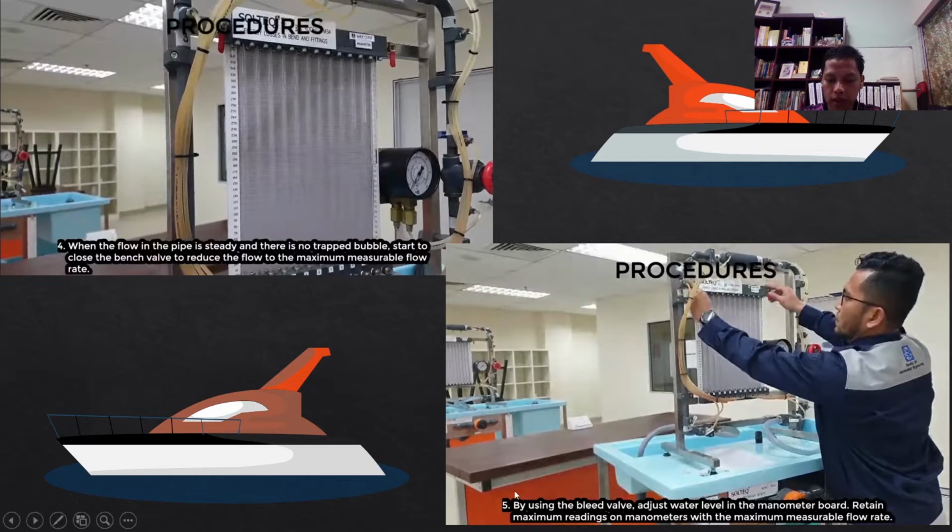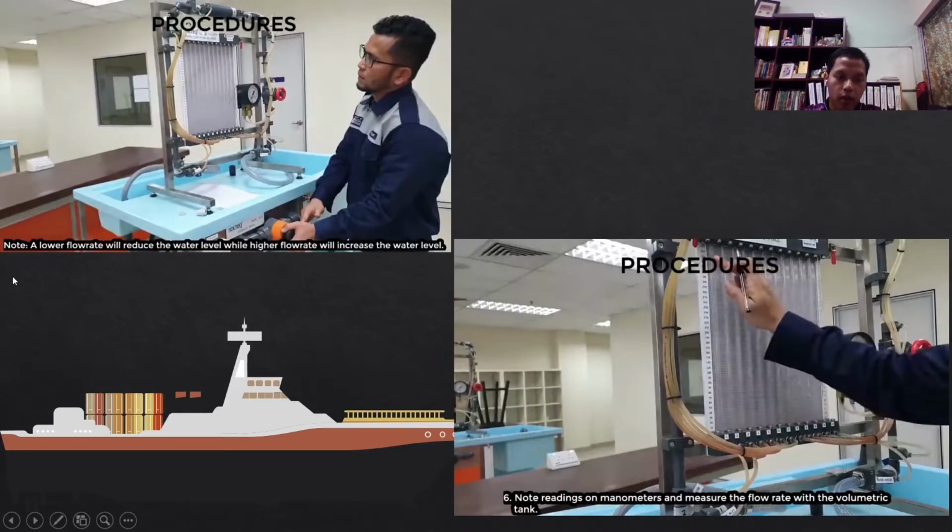Next, by using the bleed valve, adjust the water level in the manometer board, and retain a maximum reading on the manometer with the maximum measurable flow rate. Note that a lower flow rate will reduce the water level, while a higher flow rate will increase the water level.